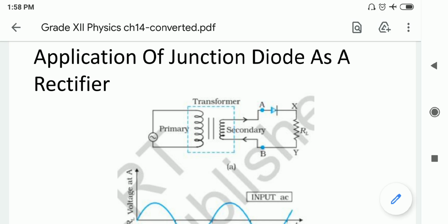This large amount of AC voltage cannot be provided to the diode directly. So first, we need to utilize a transformer which can step down the input voltage. Here we are using a step down transformer to convert 230 volt AC into a low value of AC voltage.